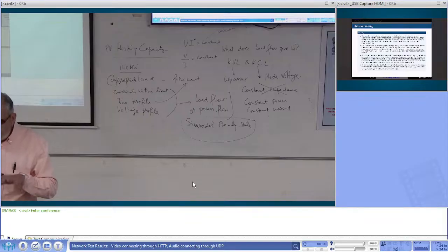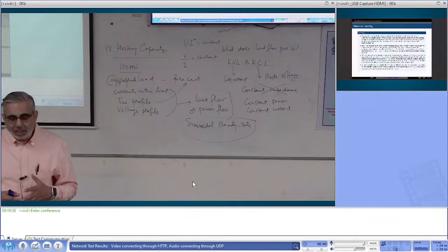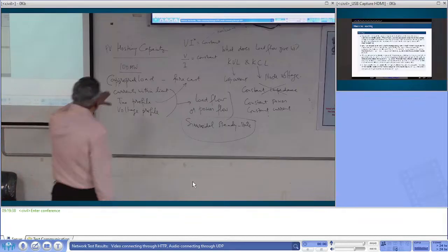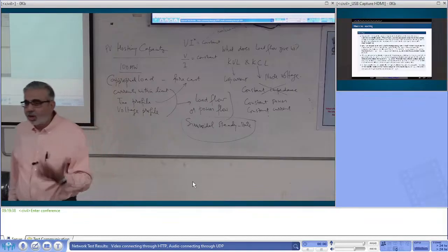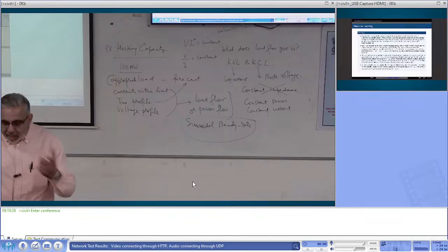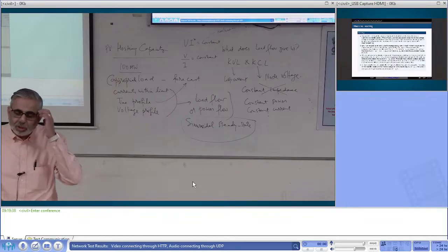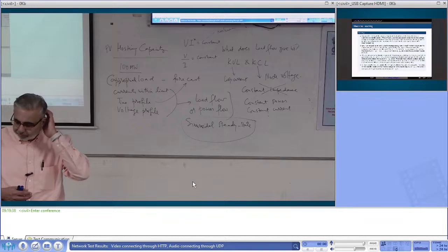Some divide it in other ways. There are many different ways they do hosting capacity. What we have been doing is, if we have got 100 megawatts of load, we use Monte Carlo or some simple technique to distribute it over the network. Once we distribute, we do another distribution, then another distribution.